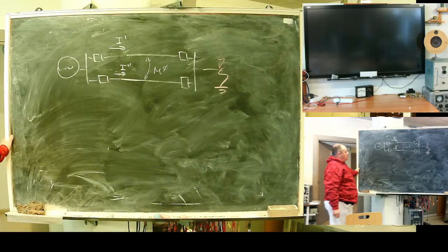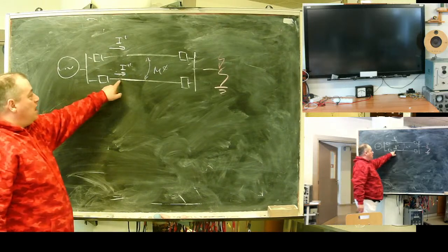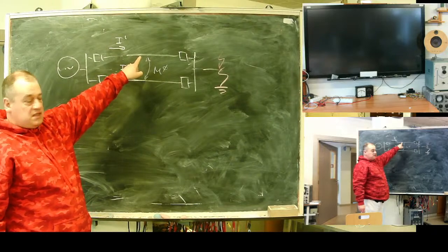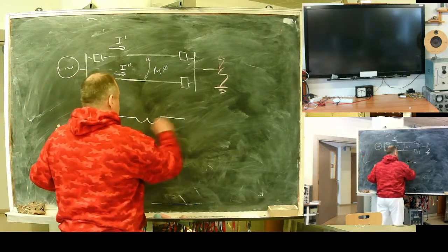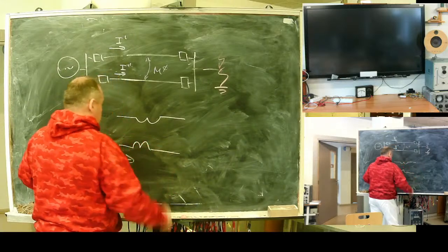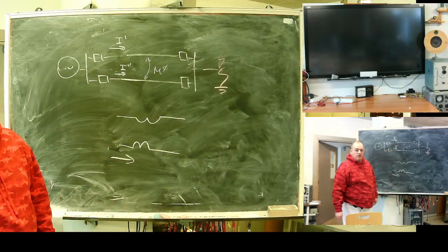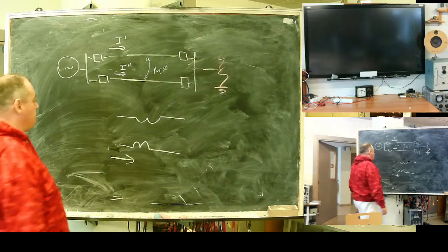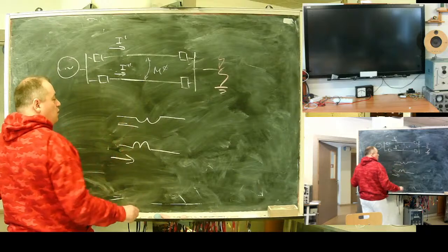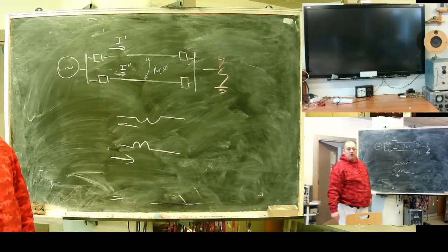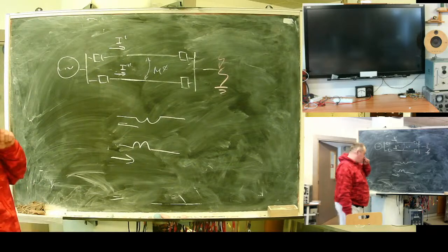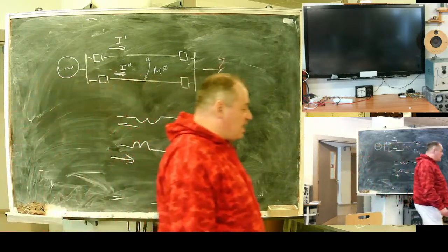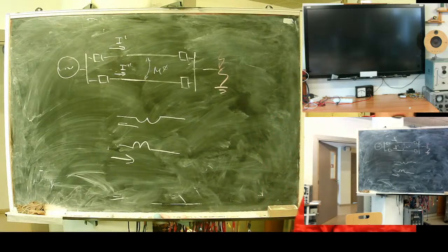As I draw it, what will the current from the second line through mutual inductance do? It will induce a voltage drop, increasing line resistance. So this current increases line resistance. For your protection, what will happen? The observable fault will move forward.